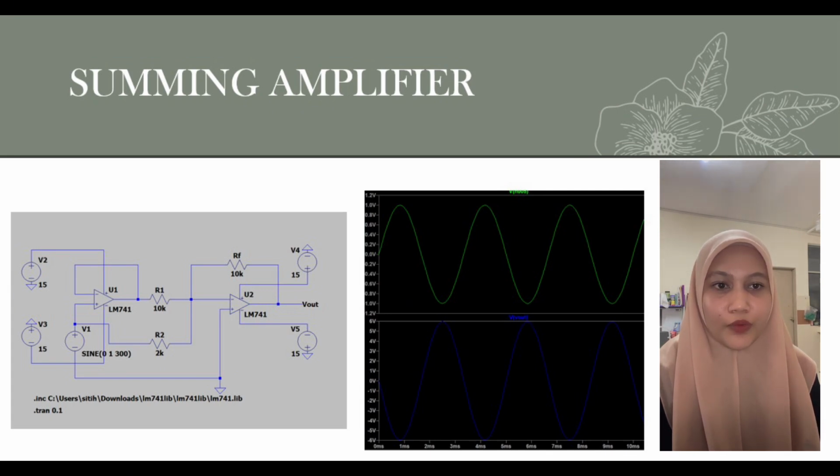Lastly, summing amplifier. The summing amplifier using 10 kΩ and 2 kΩ input resistors. We verified the output is the weighted inverted sum of the two 1 volt sine wave inputs, resulting in a minus 6 volt peak output.